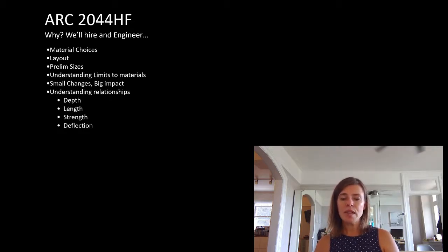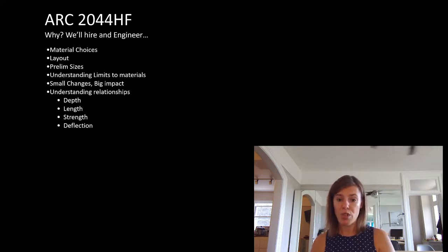You also need to understand that sometimes a small change can have a really big impact on the design, and that some of those things are very tightly tied together, like depth and length or strength and deflection. For example, making something longer isn't a linear relationship to how deep or how big your ceiling needs to be for that element. It's a non-linear equation, so you don't just proportion it up.